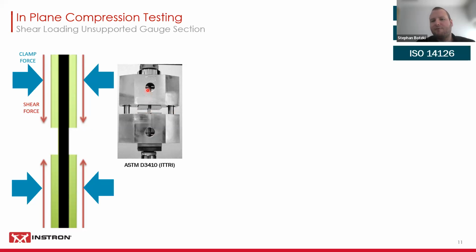It's a very heavy, very big fixture, but you can have pure shear loading. And end loading is absolutely not allowed with this testing standard. It's going to be pure shear loading. So it's going to be clamped on here within there, like you would do with wedge grips. And then on your testing machine you would put this in between compression platens. So you're end loading the fixture, but then the fixture will transfer those forces via shear onto your testing coupon.